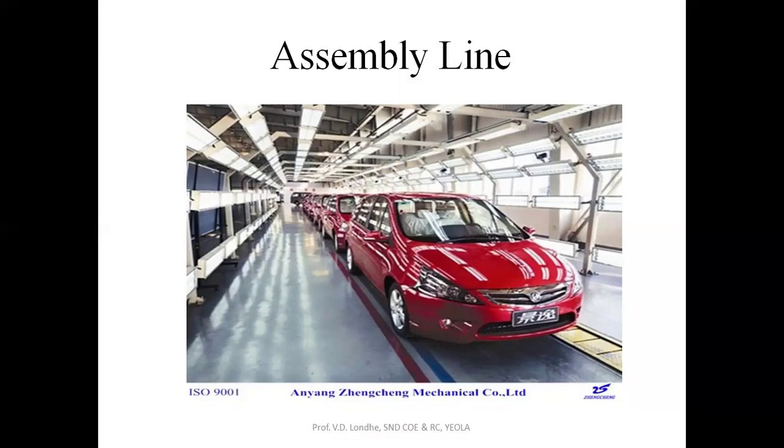In this assembly line, all the electrical connections are made. Then afterwards, filling the fuel tank also takes place in this assembly line. Then the cross connections and checking the brakes also take place in this part. Then the oil level and the coolant level are also checked in this assembly line. And finally, on the dynamometer, the emission test also takes place.